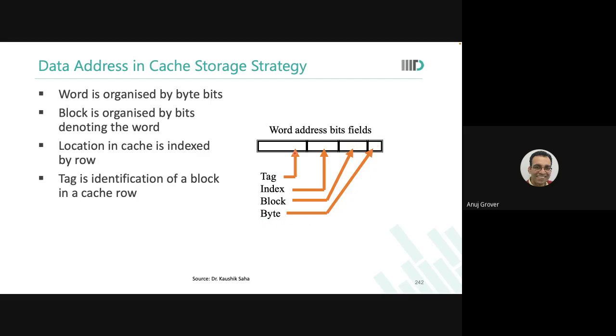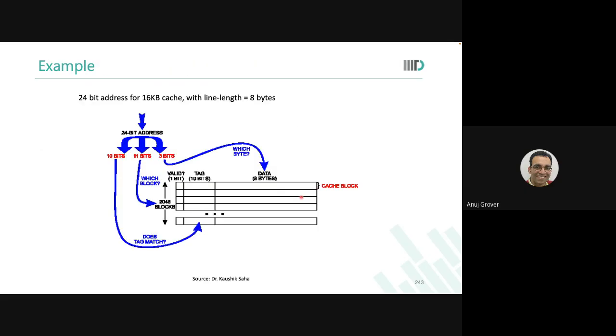Remaining everything is the address, which we have broken into tag, index, block, etc., based on how they're organized. Okay? So with a small piece of data, this is the data that you're talking about, the tag that goes with it is very big, and then you have one additional bit which is called the valid bit.